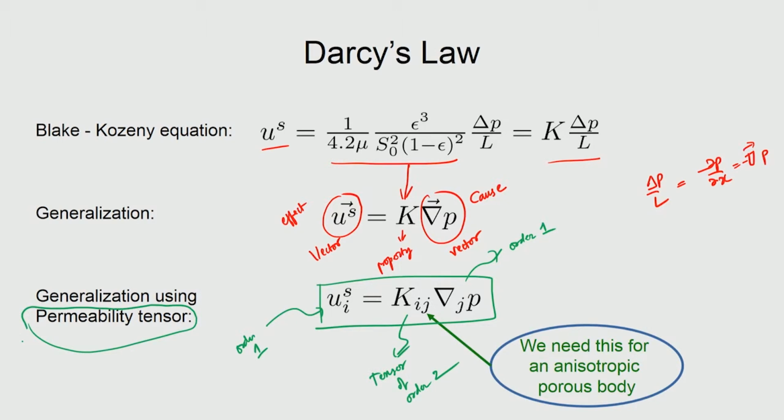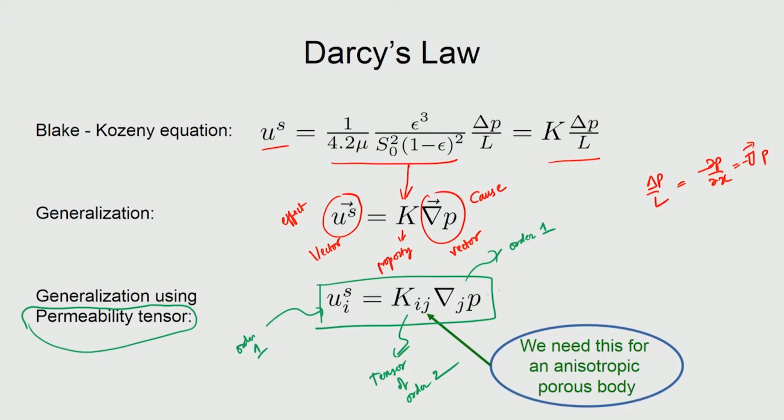So, which means that the equation that we came about by starting from the pipe flow equation and then modeling the porosity and then introducing the concept of hydraulic radius, once we got that equation, if we want, we can elevate it to the level of a constitutive relationship between cause and effect, then we do arrive at what is called Darcy's law. So, Darcy's law is this equation, in which the permeability is coming as an anisotropic tensor of order 2, and you could actually call it isotropic in situations where the medium is isotropic.